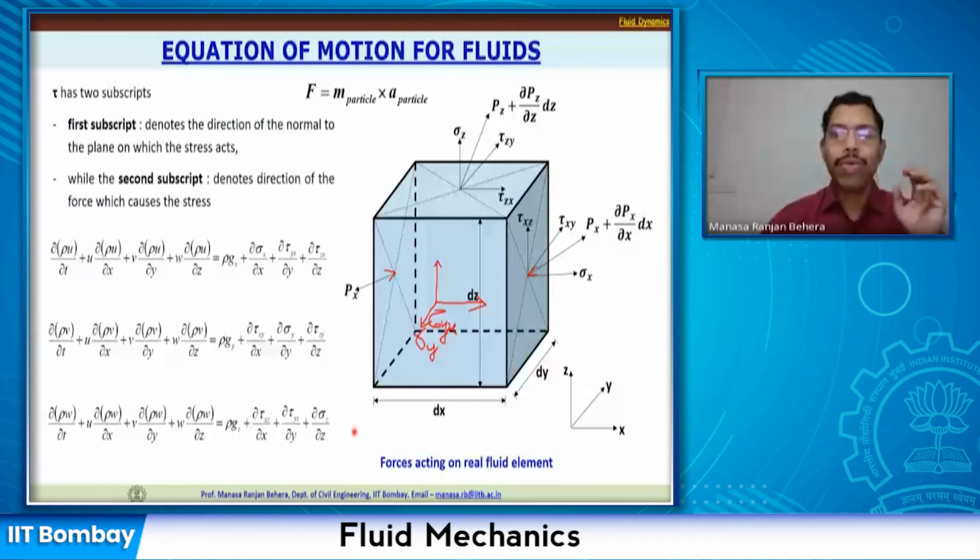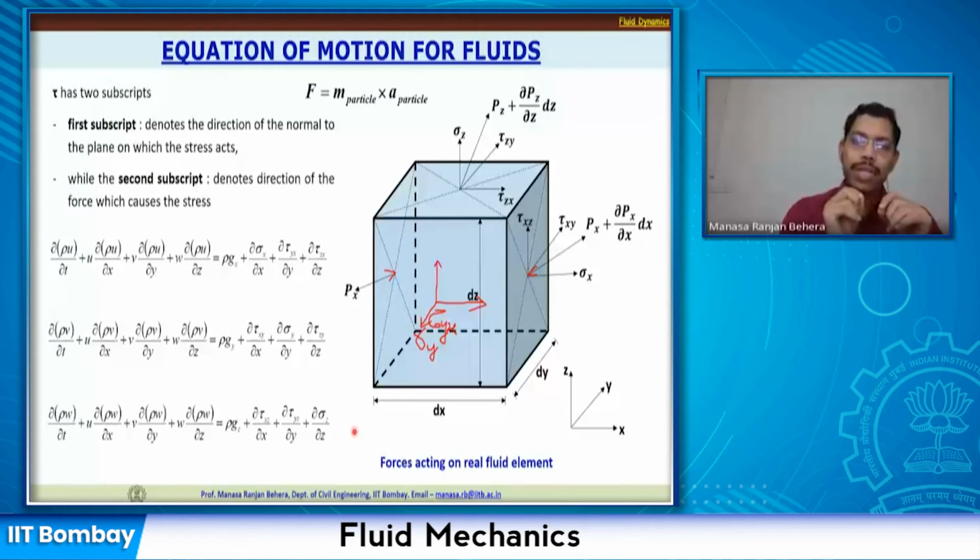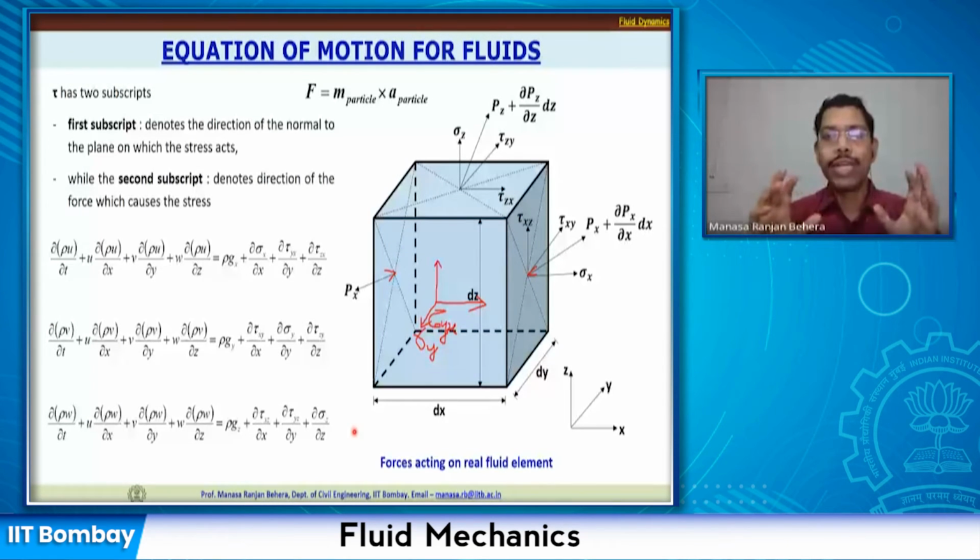Okay, so now once we have this, if we say that this flow or the fluid is a Newtonian fluid, okay, so the fluid that we have considered is a Newtonian fluid. What do you mean by Newtonian fluid? It obeys Newton's law of viscosity. So tau is equal to mu du by dy. All right. So the moment you start applying any amount of stress or force, it starts deforming. So there is a linear variation. So tau is equal to mu ∂u/∂y.